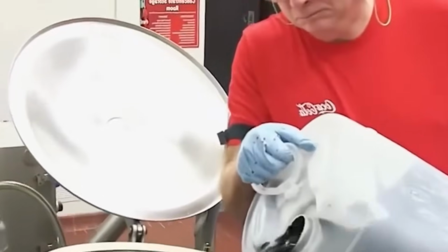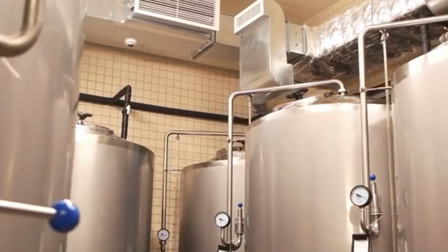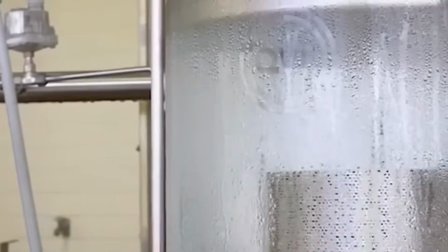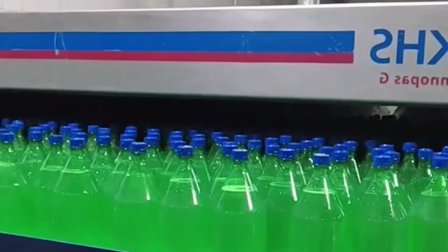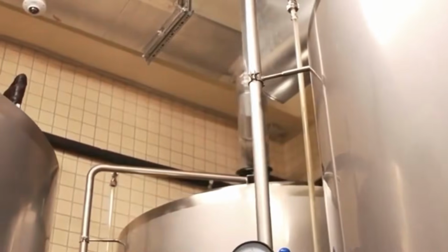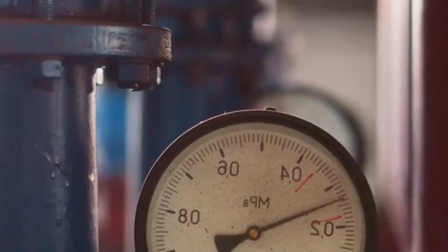The process begins by transferring liquid sweeteners, either high fructose corn syrup or refined liquid sucrose, from bulk storage tanks into jacketed blending vessels. These vessels are equipped with load cells to ensure exact quantities are used. Agitators start spinning to ensure even distribution.